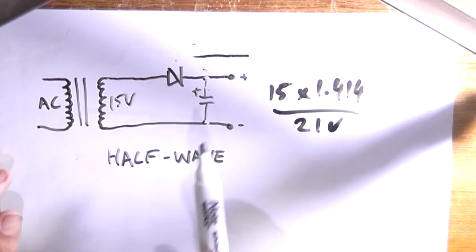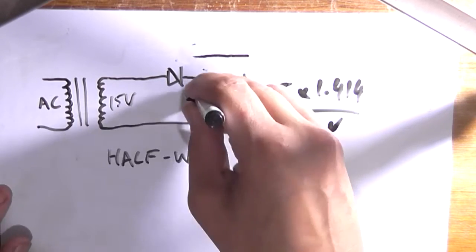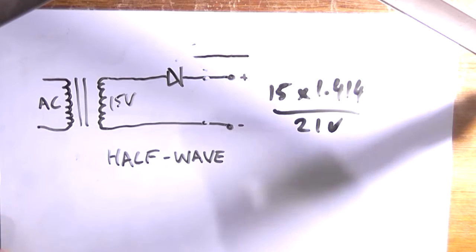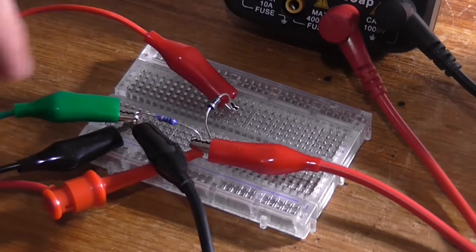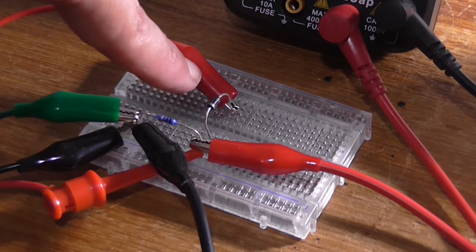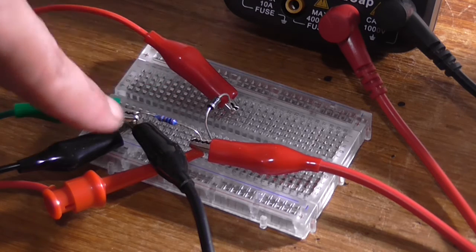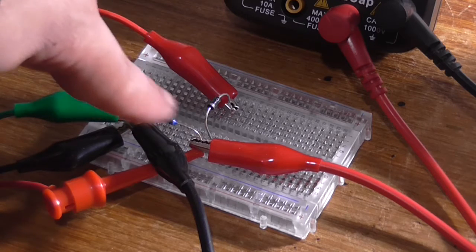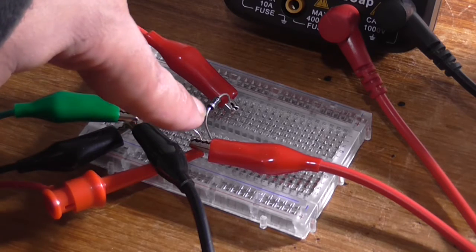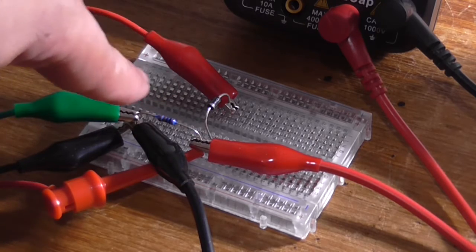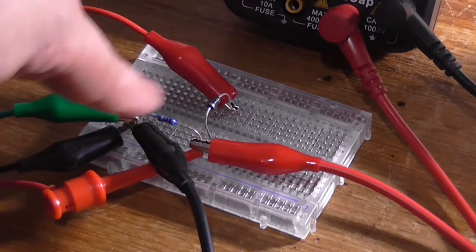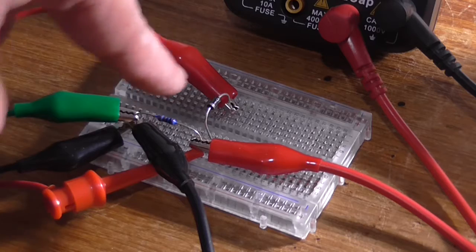after using a capacitor to filter the DC signal. So let's look at this circuit on a breadboard without the capacitor installed for now, because we'll come to that later, and just see what waveform we get out on the oscilloscope. Alright, so this is my setup. This is a half-wave rectifier, so a single silicon diode. I've got a 10k resistor here across the positive output and the negative ground, just as a load, so I'm not using the scope as a load. So it's got something to dump the current into.